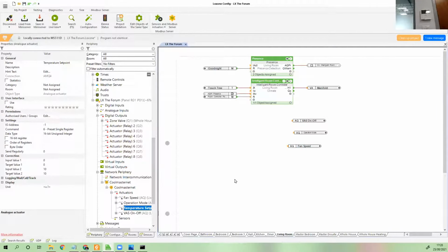Now, this is where we get a little bit interesting. When we do temperature values on things with Modbus, whether it's an AC unit or a heat pump, doesn't really matter, Modbus through signed and unsigned registers can't go to decimal values. It can only do whole values. And of course, depending on the unit that we're speaking to, we may well want to set something like 21.5. So how do we achieve that?